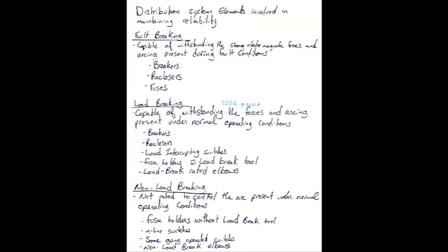For those, we need a switch that's built even tougher. Something that's got a lot of resiliency and very, very strong actuation involved, so that it can break tens of thousands or more amps worth of fault current that are flowing through it. And for those, we tend to see that breaks down into three classes. We've either got breakers, and breakers always come with an associated relay. Later in the course, we'll dig into those a little more. A recloser, or a fuse.